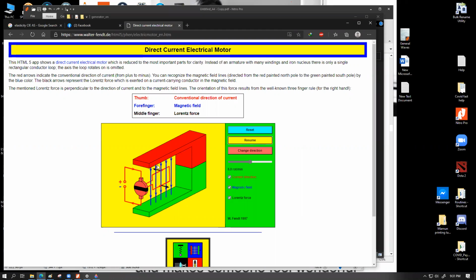That is when at this perfect orientation, the two forces will have the biggest amount of torque generated. The force would be same throughout the motion. That's why the black arrow lengths are not changing, because F equals to BIL. For every single orientation of the wire, the BIL is the same for a single wire. But how much torque you get out of that force is a variable dependent upon how much perpendicular distance is available across those two forces. That is going to become weaker as the coil slowly becomes perpendicular with the field.